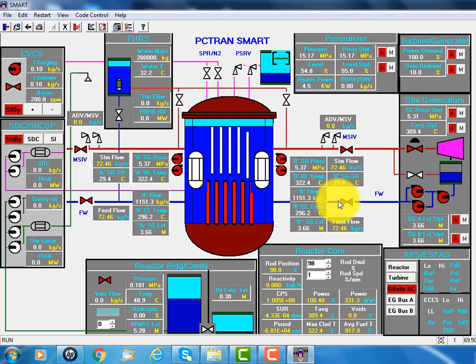The feed water going from the bottom is spiral coiled and heated by the reactor cooling hot water, becomes steam, and the steam is superheated because of the once-through steam generator. The steam goes to the turbine and the generator, and then is condensed in the condenser, and a number of heaters and pumps send it back into the reactor.